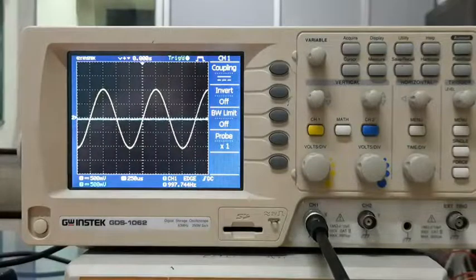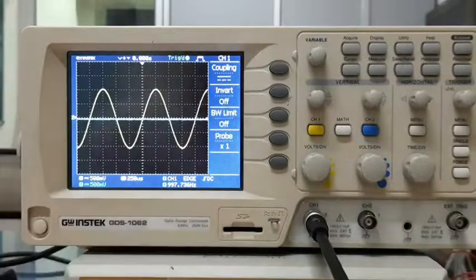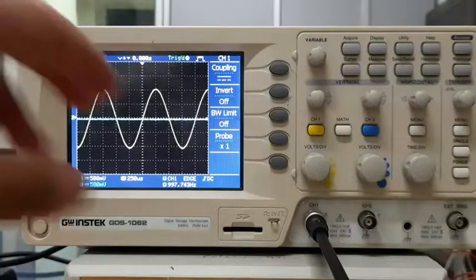One is DC, which is shown as a flat line, as a straight line. So that's DC coupling, and normally you should always remain in DC coupling mode, right? Because in DC coupling, the oscilloscope is able to measure DC as well as AC. In AC coupling, it only measures the AC component, it filters out the DC component, and then there is a ground coupling in which it simply shows the reference level, it does not measure anything, right?